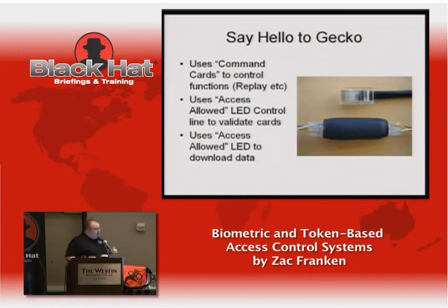So there tends to be no tamper proofing on the readers. They are standard kind of devices generally. This is designed to fit on a standard J box, junction box on the wall. Same as your light switches. So literally, to prevent you getting at the actual wire transmitting the Wiegand data, you have 2 screws and a plastic cover.